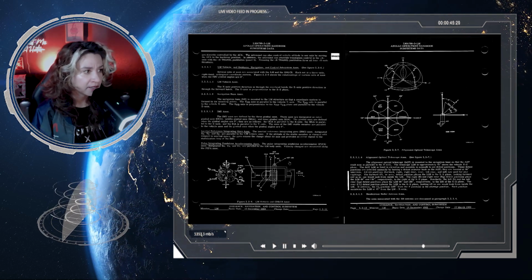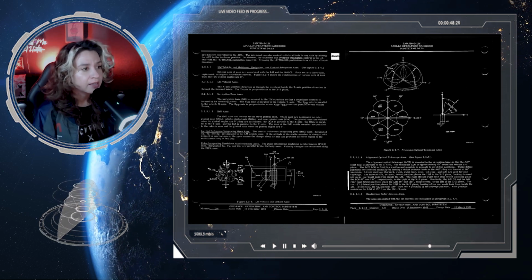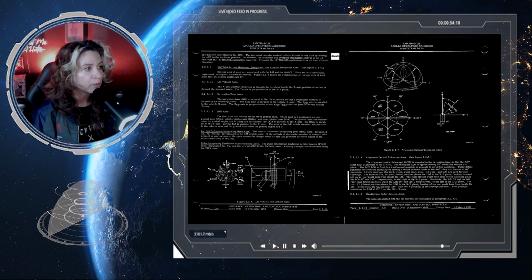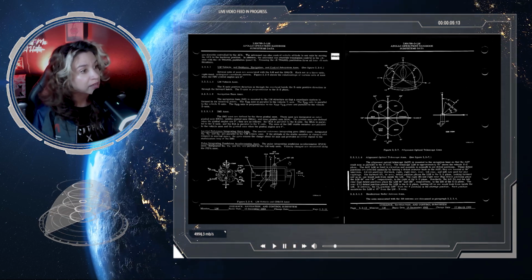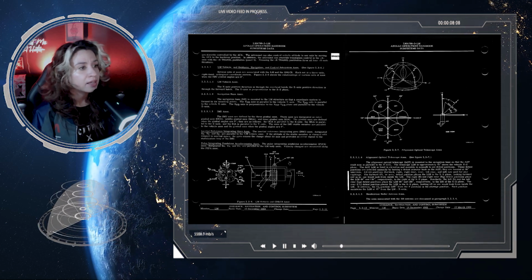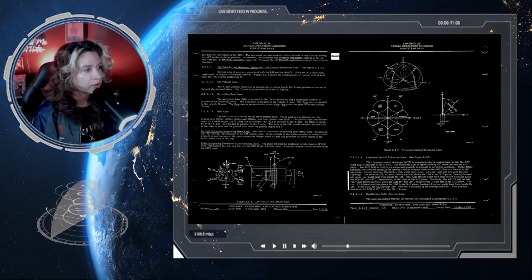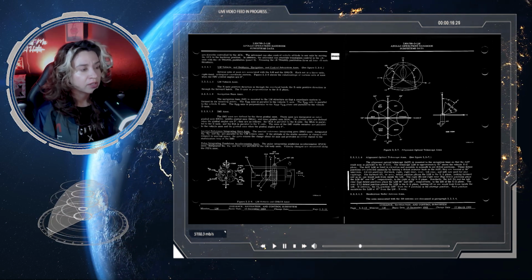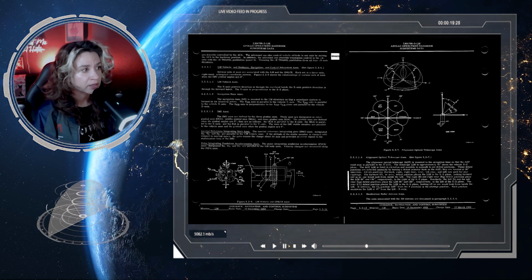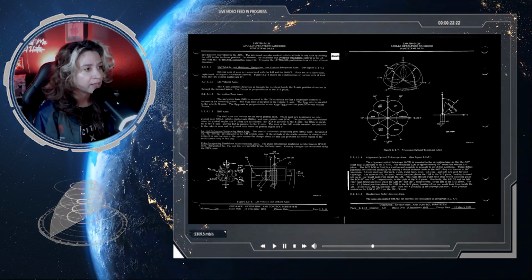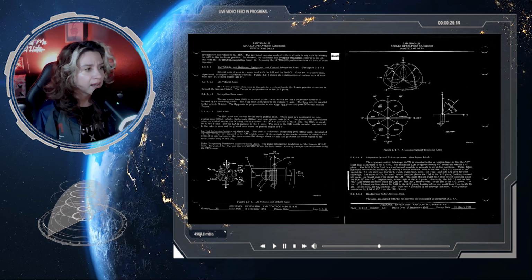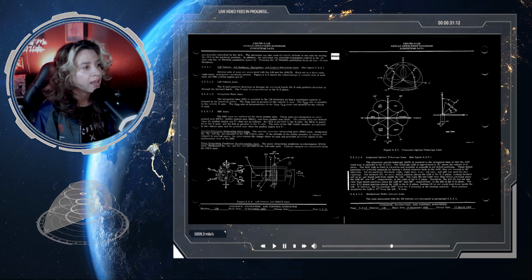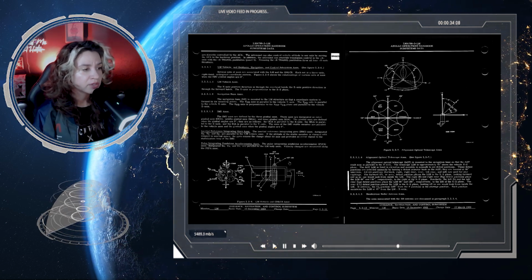The IMU axes are defined by the three gimbal axes. These axes are defined as outer gimbal axis, or the OGA, middle gimbal axis, or the MGA, and the inner gimbal axis, the IGA. The gimbal axes are defined when the gimbal angles are at 0 degrees. They are as follows. The OGA is parallel to the x-axis, the MGA is parallel to the z-axis, and the IGA is parallel to the y-axis. The axes of the IMU stable member are parallel to the vehicle axis and the gimbal axis when the gimbal angles are at 0 degrees.